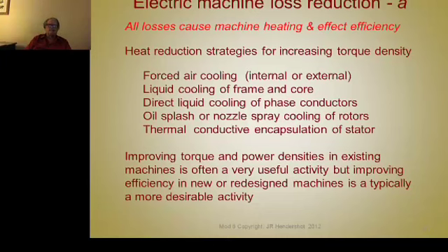outside of the stator. So it's not uncommon to assemble cores in rotors and stators with cooling passages through them, with vent spaces between sections of the core, and the conductors in the stator and the rotor pass through these cores and are exposed to whatever cooling media is pumped through those.